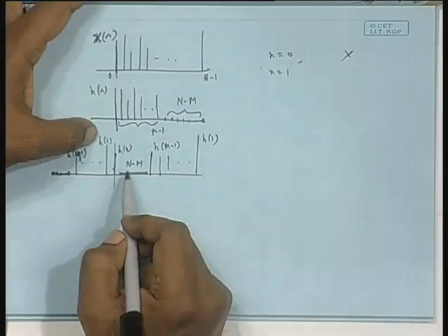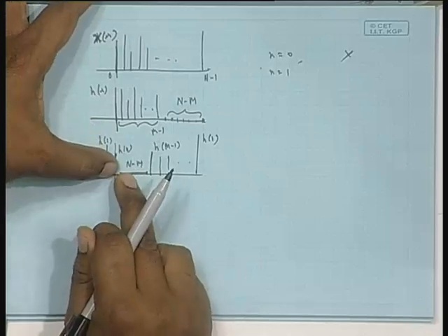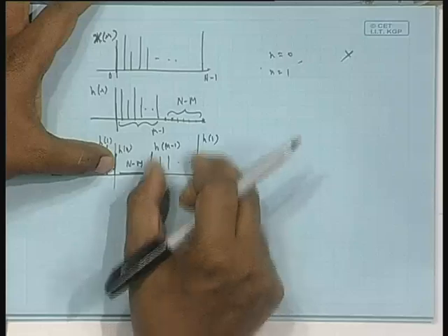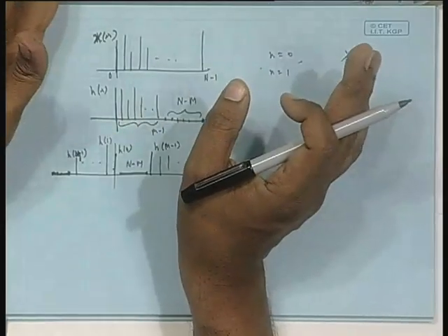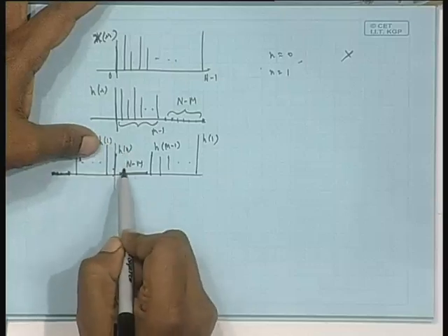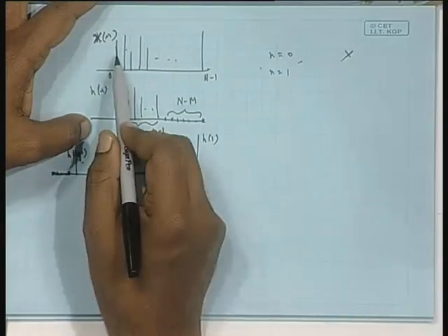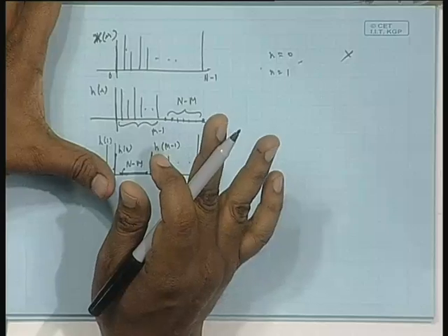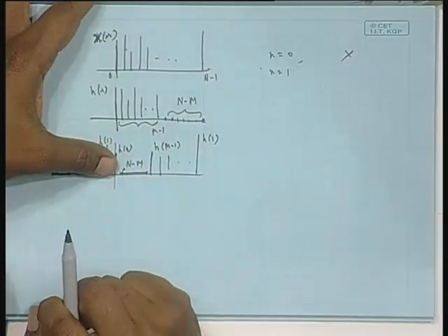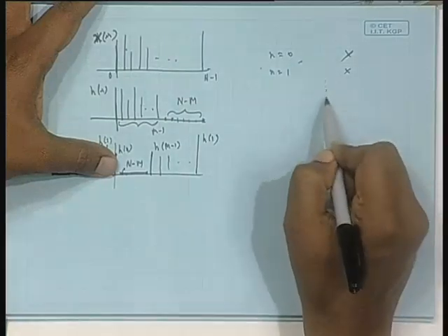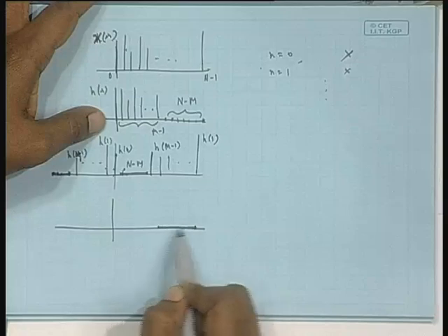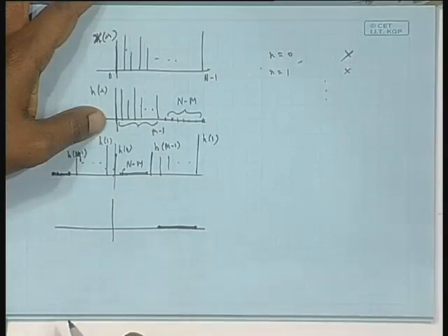Okay. At n equal to 1, these two will move up, one sample of the 0 pad will be moved out, but still these fellows are there, they will multiply with the samples from the top and will give rise to error. The left of the 0 pad is fine, h 0 below x 1, h 1 below x 0, that is the linear convolution thing, is it not? But these fellows are creating trouble. So, this will be incorrect, dot dot dot, it will continue till the point where this 0 pad reaches here.